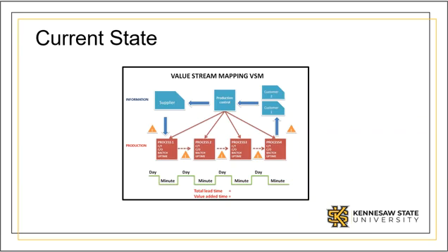Cycle time can also be useful. This is the time it takes a piece to complete an individual process. It would also be suggested to note the uptime of the process. This gives us an indication of the reliability or robustness of the process step.